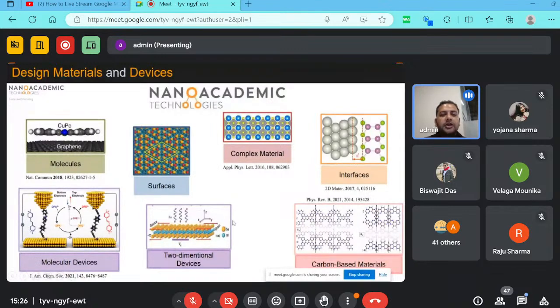Some two-dimensional material-based devices, where you can define some material. Let's suppose you have a MoS2. With that MoS2 you can create the nanostructure, and then you can assign some left electrode, some right electrode, and then a two probe device you can simulate. If you want to define some gate also, the transistors, then it is also possible.